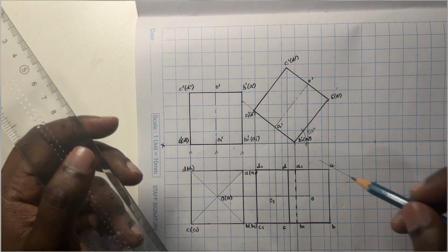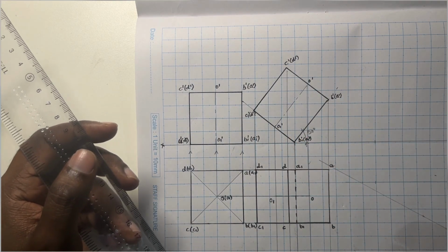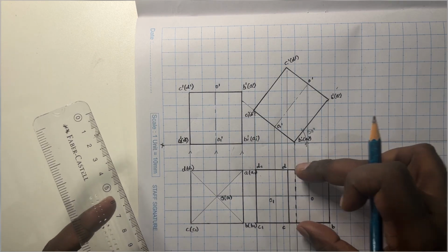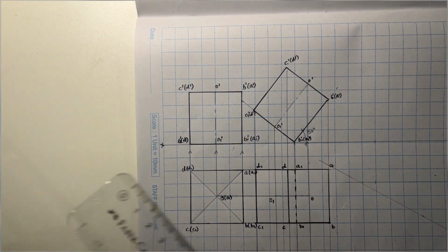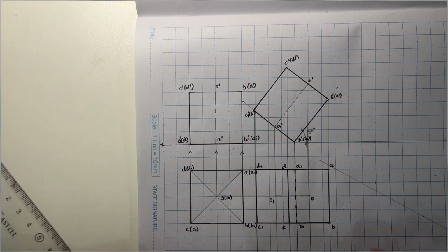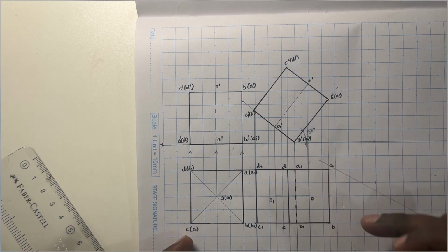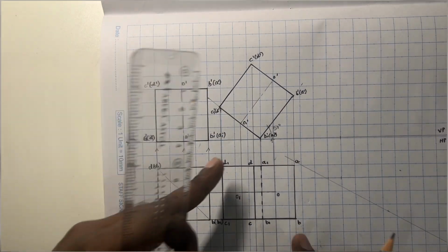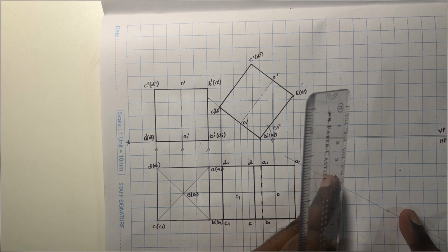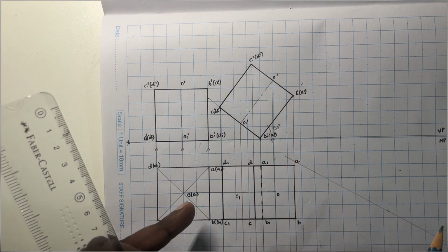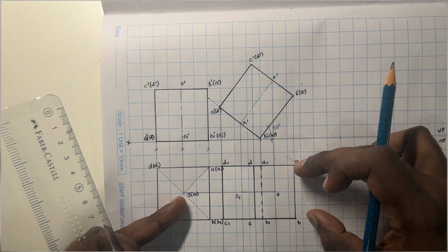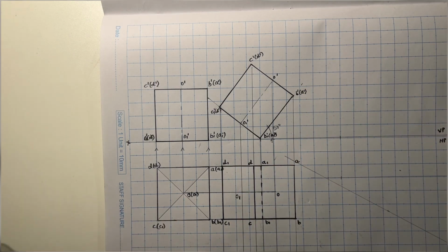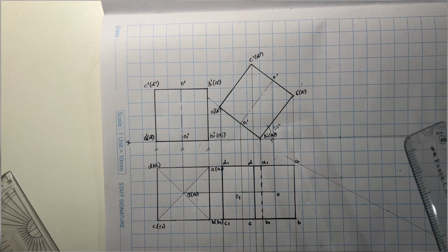So this line, when extended, is making an angle of 30 degrees. On this 30 degree line, I need to transfer first the edge, that is A1 and B1. Also ensure that whenever you're transferring A1 and B1, you're rotating the cube on this 30 degree line, and when you're doing so, the outer edges, that is AB and D1 and C1, must not cross the XY line.